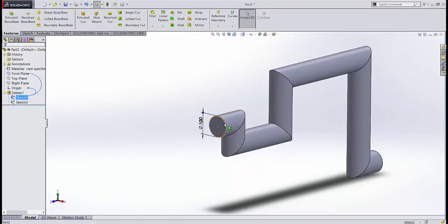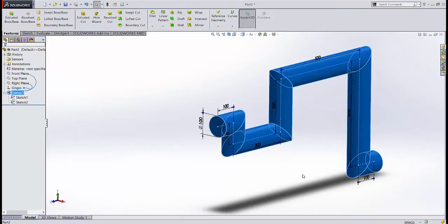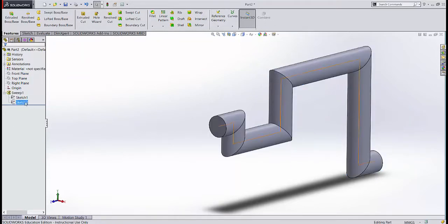Sketch 1, which defined the profile to be swept, has not changed. Sketch 2, which defines the path along which the profile is swept, was changed to this meandering path that exists on the YZ plane. You'll note that SOLIDWORKS has automatically created the tangencies that are necessary for these parts to fit together along the sweep. If you define your path incorrectly, SOLIDWORKS might not be able to solve the sweep path.